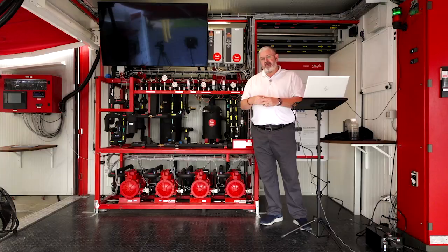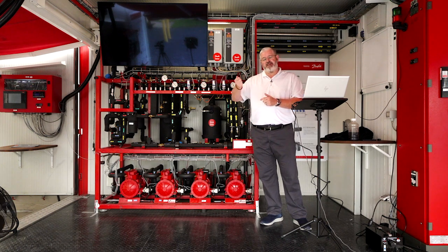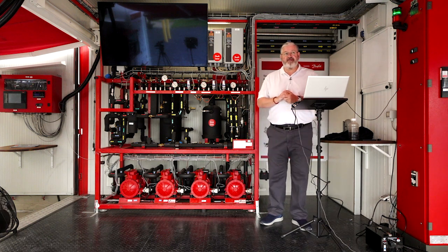If you wanted a cost-effective way, I believe it's underutilized in my opinion, but I believe the single condensing unit that's just meant to handle load in a power outage situation, because you've got the heat exchanger that'll deal with whatever pressure's built. It'll keep pressure from building in the flash tank, and it's a very small load to have a generator for. So I think a backup condensing unit with a small generator and a heat exchanger to keep the temperature of the flash tank from reaching the relief valves would be the best option.